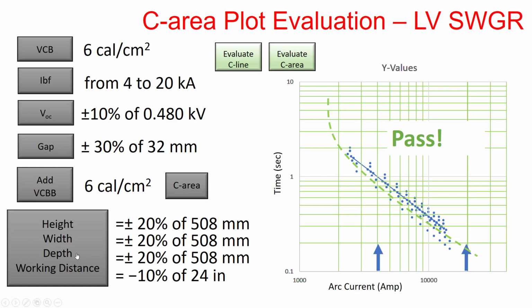And last, we can define a boundary for our C area points. This is the boundary of the combinations where we yield the lowest current and higher incident energy, lowest energy, and lower currents. This boundary area now represents all potential combinations and forms that this arc can live with within that equipment and allows us to set a constant energy value to it. If we perform a similar evaluation as we did in the past, we would see that the evaluation actually fails,